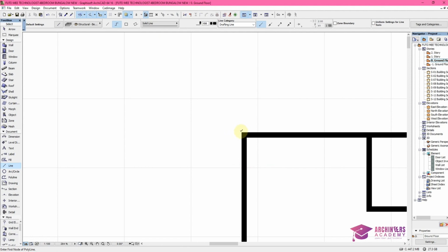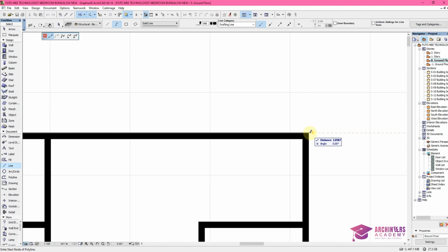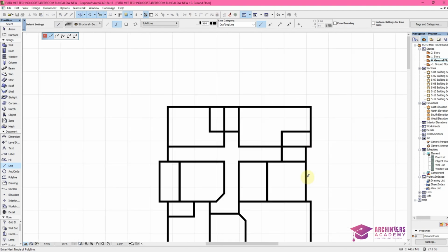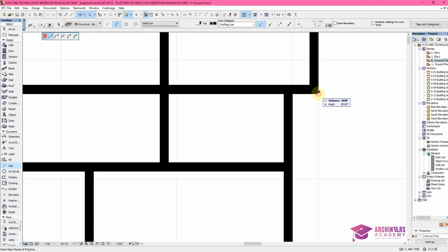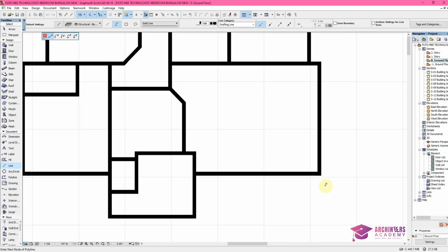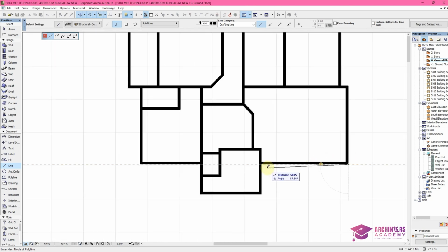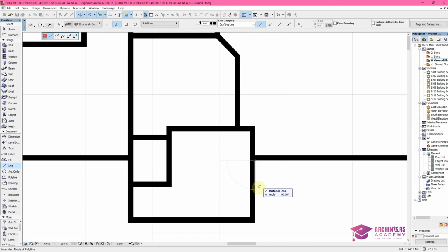In an architectural site plan, one of the thickest, if not the thickest pen weight in the site plan is usually the shape of the building. It's actually the shape of the building. Then maybe followed by the boundary line, and then other things, and then the floor is going to be the last, or the least of them all. So I'm going to use the thickest.